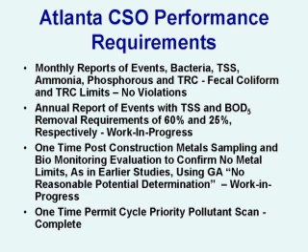grit, and then it goes down to the sedimentation basins where sodium hypochlorite is added to the flow before sedimentation. After sedimentation, it goes through compressed media filtration, and then it receives sodium bisulfite for dechlorination, then is discharged into the river. There is also, in the upper left-hand corner, an overflow from the tunnel. So once the tunnel is full, it could actually then discharge out of the tunnel system for rates above the CSO treatment capacity. So there's a couple of places the flow can actually be discharged from the tunnel system.